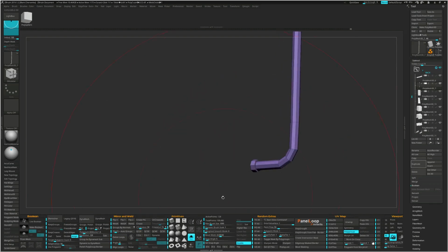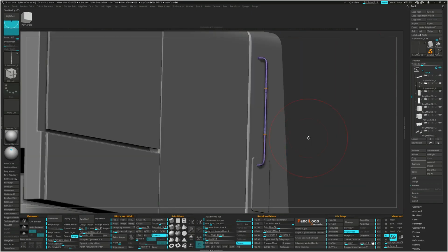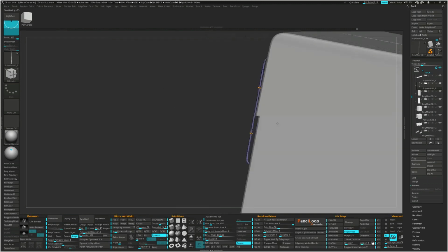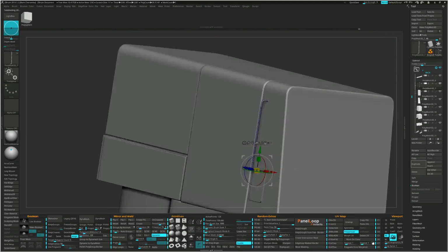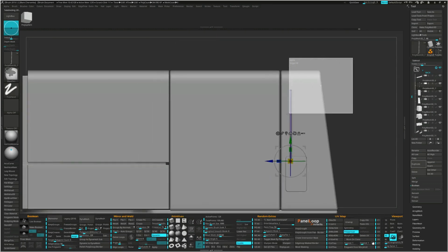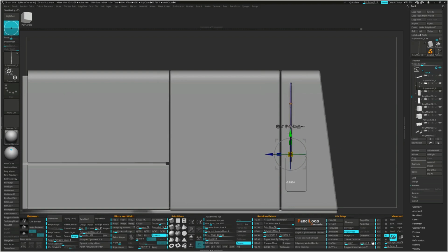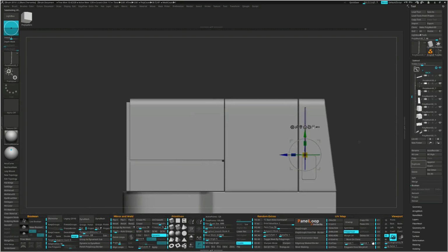The QC50 button I pressed on my UI is a quick crease with an angle tolerance. So it creases my object based on a 50-degree angle, turns on dynamic subdivisions, and sets the smooth subdivisions to 4. It is from a free plugin that was made by Joseph Drust called Drust Tools. It's a very useful plugin.